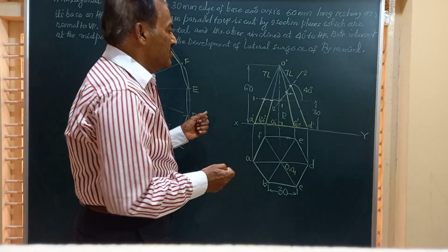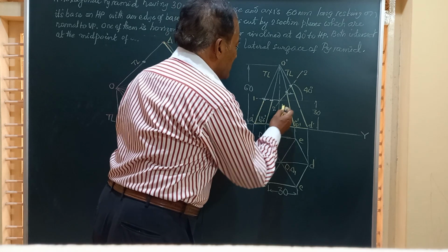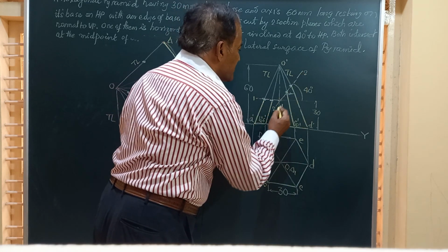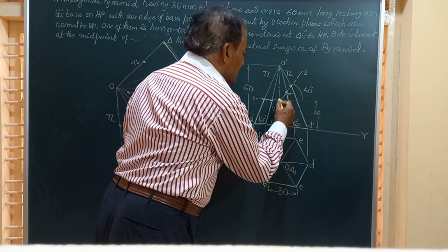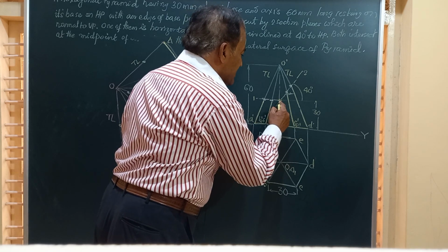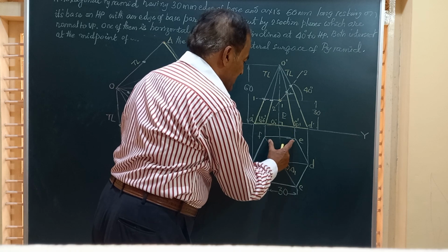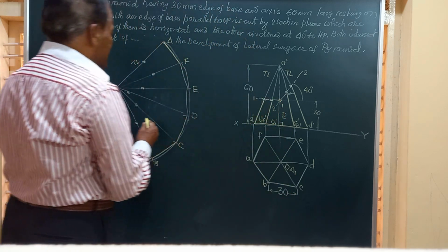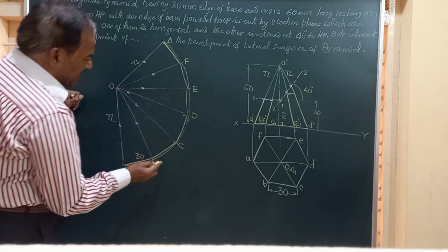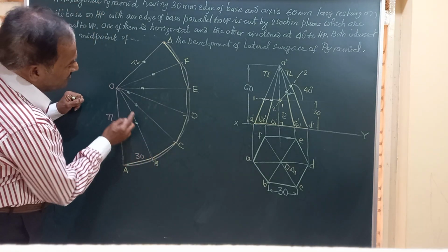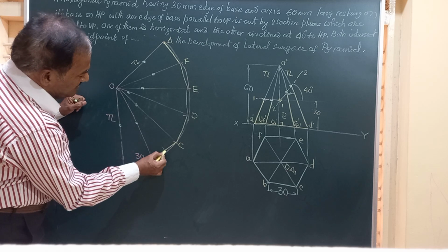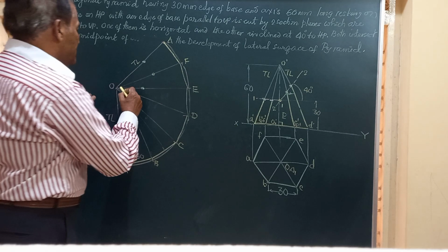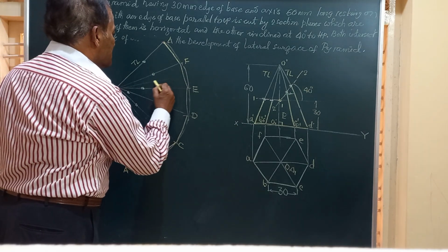I will show you. See, here the section plane 1 and section plane 2 are meeting here. So this point is exactly between FE and BC. So you have to mark one more point between BC and FE. So friends, BC you have got here. You draw a thin line through that. And similarly FE, another line through this.